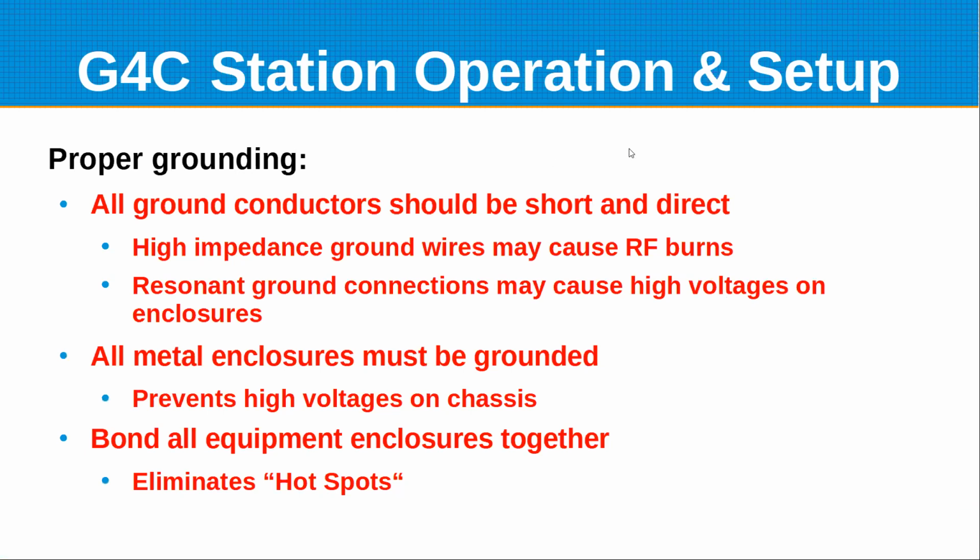Okay, proper grounding. All ground conductors, you want to have them as short and direct as possible, meaning no loops or sharp bends, which increases the inductance of the wire and increases the impedance at higher frequencies. If they're excessively long, they can become resonant at some frequencies, so you'll see some high voltages due to the resonant RF on them.